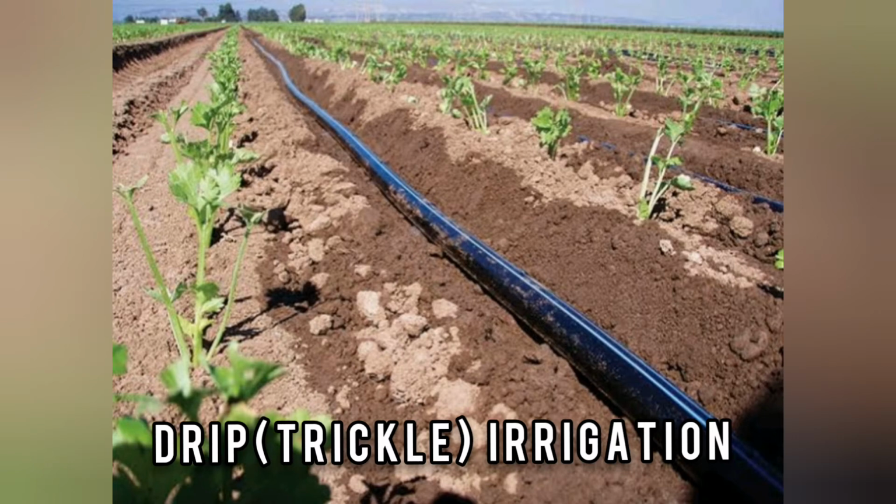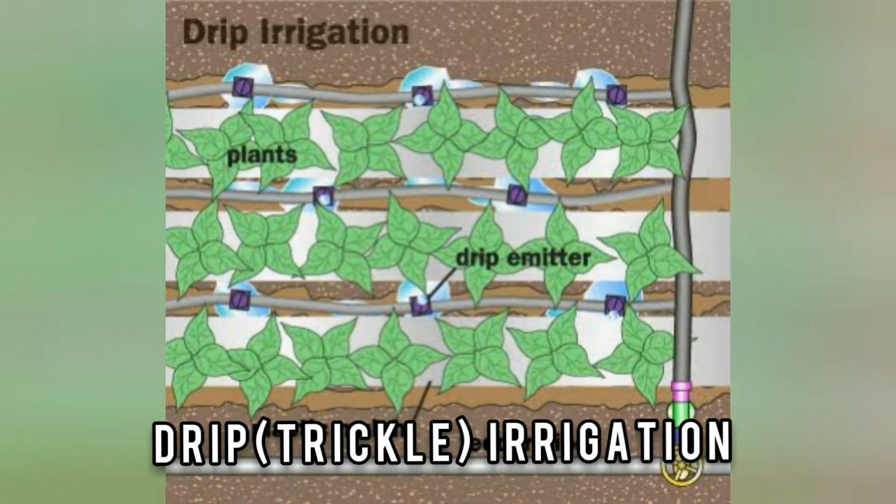The fourth method is drip irrigation. It is also known as trickle irrigation, and functions as its name suggests. In this system, water falls drop by drop just at the position of roots. Water is delivered at or near the root zone of plants, drop by drop. This method can be the most water efficient method of irrigation. The field water efficiency of drip irrigation is typically in the range of 80 to 90% when managed correctly.